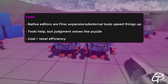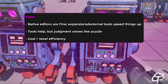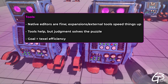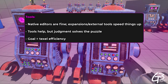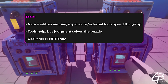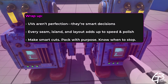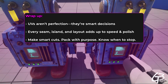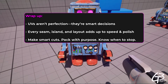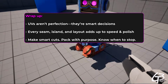Tools help, but they don't think for you. Native UV editors are fine, but native tool expansions or dedicated external UV tools can seriously speed things up and improve quality. But even with great tools, UVs are still a puzzle. You solve it with experience, judgment, and a clear goal, texel efficiency. So yeah, UVs aren't just technical, they're strategic. Every seam, every island, every layout choice, it all adds up to performance, polish, and production speed. So make smart cuts, pack with purpose, and know when to stop.